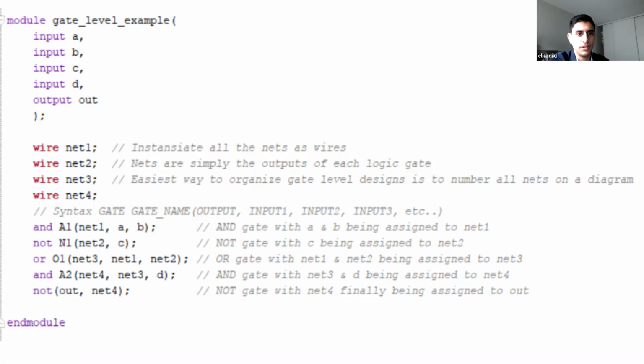All right, is anyone still typing away, or are we good to move on? By the way, just do a Control S and look out for any syntax errors you have. If it's complaining about something, look around, make sure you're not missing a semicolon. Make sure you didn't misspell any of the net names or the input names. All right, I think everyone's good.